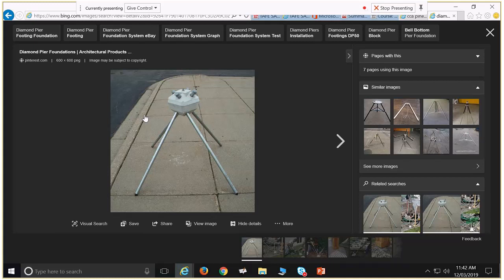Although where it would get really labour intensive is where you're ramming into soils that have a lot of rock and shale and things like that. And that's probably the biggest limitation that comes straight to mind, is you can't really ram these bits through stone. And if you've got a site which is sheet limestone about 200 mil down with a sandy top to it, no way you can use that. So you have to think about your site, and probably if you're building on sand, you probably wouldn't want to use those on sand either.